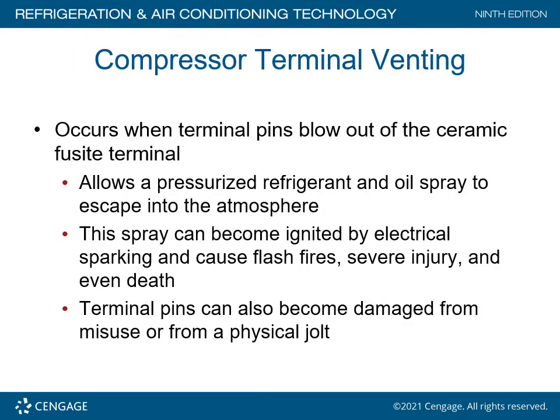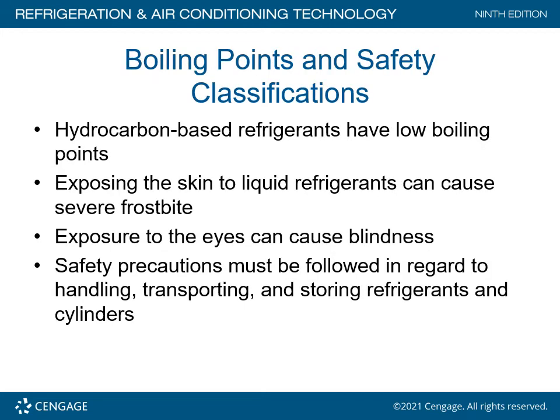Compressor terminal venting occurs when the terminal pins blow out of the ceramic fuse type terminal. It allows pressurized refrigerant and oil spray to escape into the atmosphere. This spray can become ignited by electrical sparking and cause flash fires, severe injury, and even death. Terminal pins can also become damaged from misuse or a physical jolt.